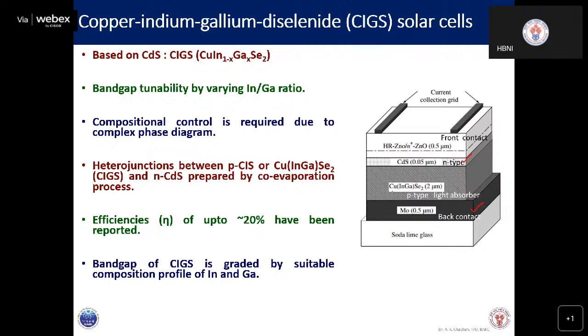So you have copper indium gallium selenide here, about 2 micron thickness, then above that you deposit cadmium sulfide, then over that you have a front contact of zinc oxide, and then the back contact, and after that there is glass. So the deposition takes place in the opposite order, say you have a glass, then the back contact, then the front contact, and then the current.